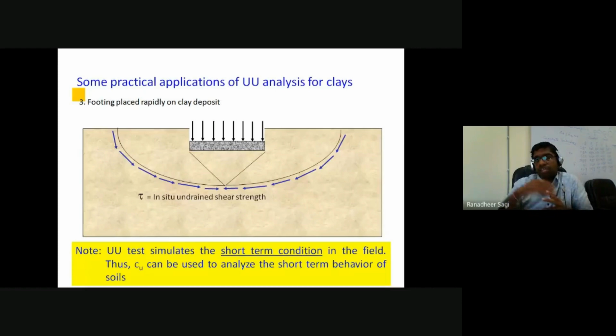And after a sufficient amount of time, if I want to know the strength of the soil, the strength now would be different from the strength of the soil after some sufficient time. Now, why is the strength of the soil changing over time? Because now the soil might be in an undrained state because of the loading that is continuously being applied. However, with the increase in time, due to the load applied on the soil, excess pore water pressure dissipation might have happened, and the condition of the soil would be different from the original initial condition.